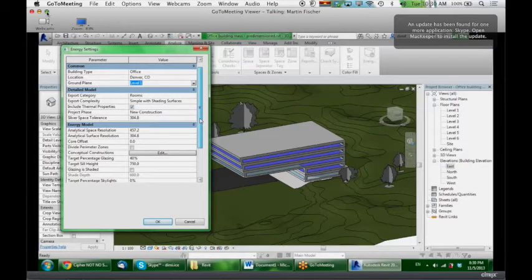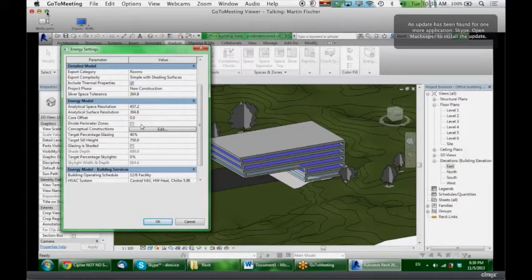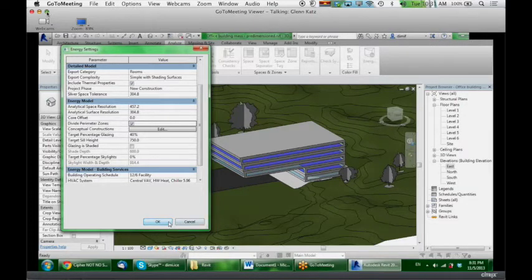Then we have the energy model assumptions that we might need to take a look at. The first 3, 4 of those aspects, I think we're going to keep them for later. For right now, I would urge you to uncheck the perimeter zones. What this does is automatically divide the building mass into usage zones, like which parts of this mass are being used by people at what distance from the walls. Right now, turn it on for a second. We'll see the impact.